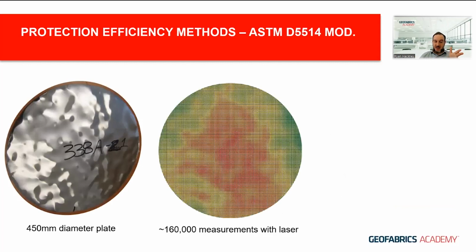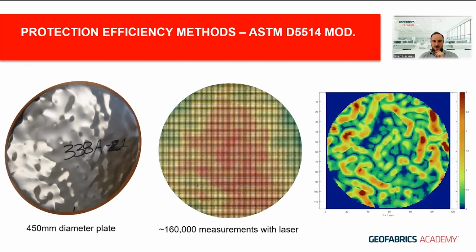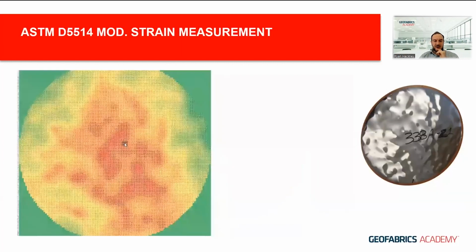That aluminium plate then gets laser scanned with a set level of precision. The laser scanner is actually capturing those vertical deformations every square millimeter. So if this is a 450 mm diameter plate, there's about 160,000 measurements taken with that laser to record the deformation at every square millimeter. And then from that, we can do some calculations, which I'll talk about, that convert those deformations into strain.